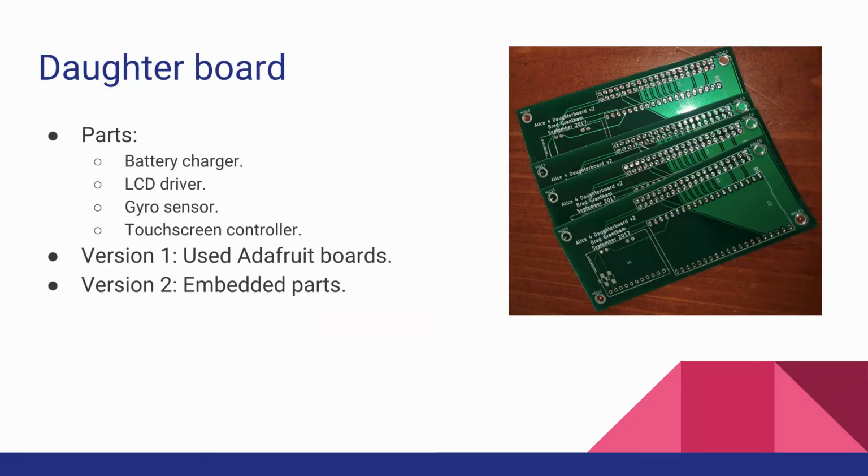Okay, so the board itself does almost everything we needed, but we need a few other things. A battery charger and a discharger, the whole logic of charging a battery, getting it back, and monitoring the battery. So that's an Adafruit board. The LCD data is fine, you can take that straight from the FPGA, but you need something to drive the backlight. The backlight is a constant current LED, so you need an LED driver for that. That's also either Adafruit or SparkFun, I can't remember.